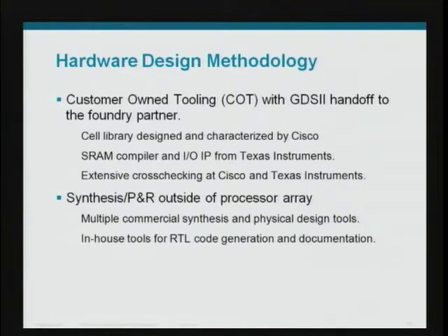The design methodology, a little bit on that. This was a customer-owned tooling, or COT, design. We handed to Texas Instruments a completed GDS2 tape. One thing that was done, though, was they ran their complete suite of physical design checks on our data.